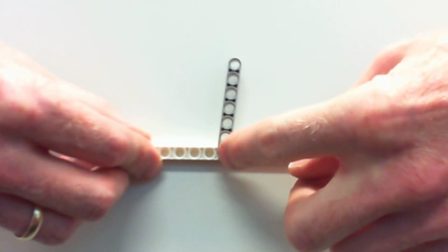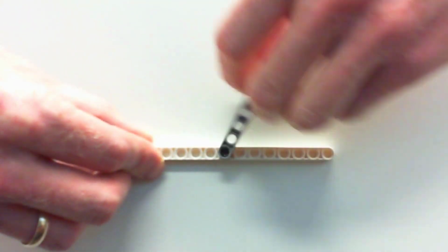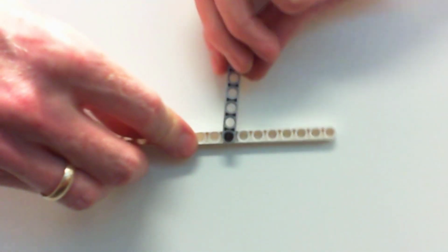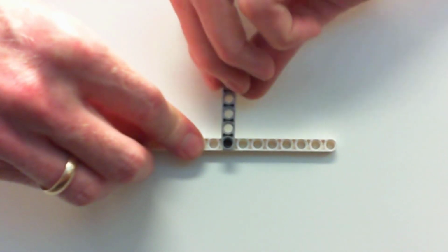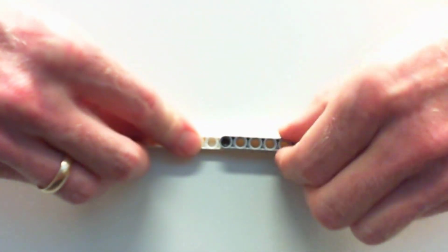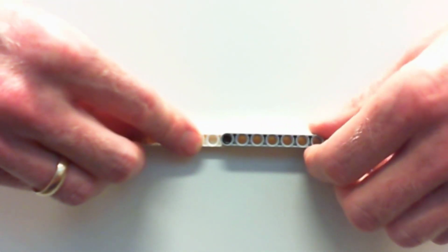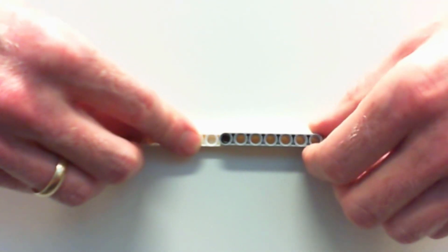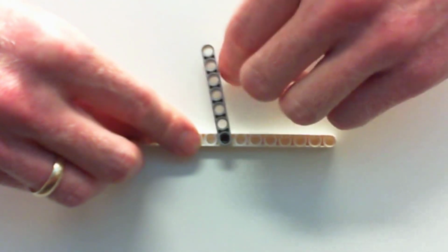So we're assuming here that this black pin is frictionless, that this can rotate friction-free in any direction that it wants to go. But if we try to pull on this, and if we want to assume X and Y components to the forces, I could pull this direction. I could also pull or push this direction, and it's not going to move. Okay, so it has a resistance to translation in two different directions, two different degrees of freedom. And so we have two unknowns.